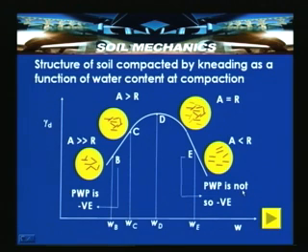We have discussed in the previous class that the swelling of a soil compacted at water content B is more than that of the soil compacted at water content E. At water content E the soil swells less, because there is already an abundant availability of water surrounding these particles, or the full development of the adsorbed water layers has already occurred here.